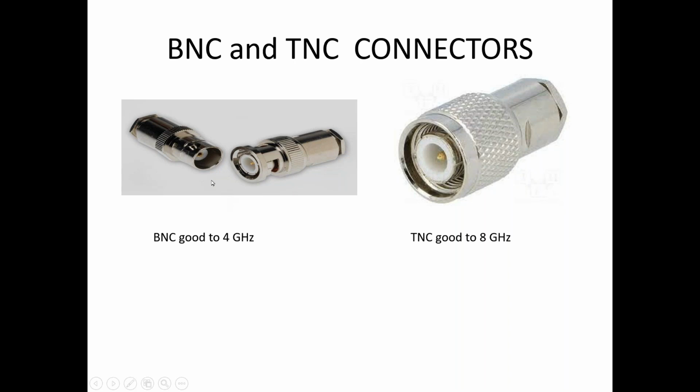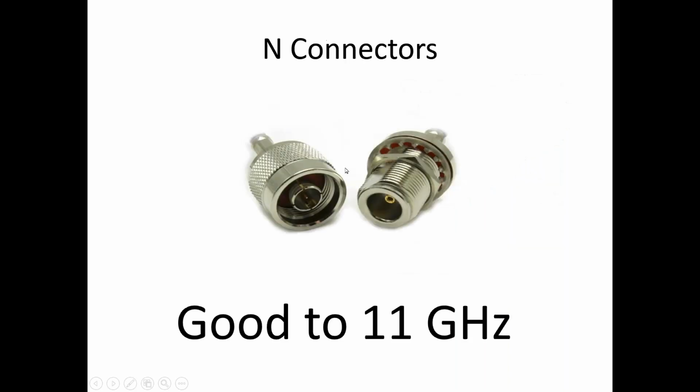Bayonet, threaded. Bayonets are great for quick connects. You've seen them all the time. Not so great for something that's constantly moving around because it's spring loaded. That spring can be affected by the movement, and thus you have a threaded Neill-Concelman, which will give you a tighter connection. Here's an N connector. These are good up to 11 gigahertz of frequency.